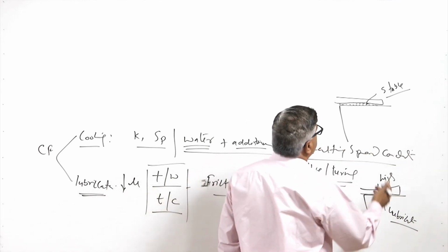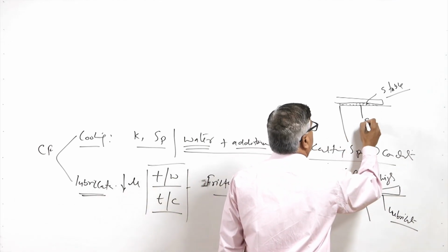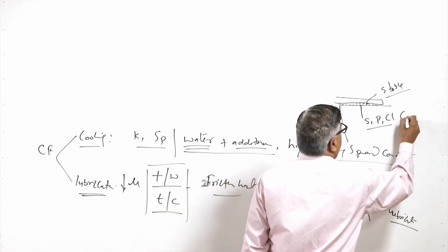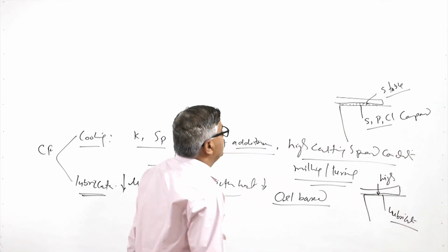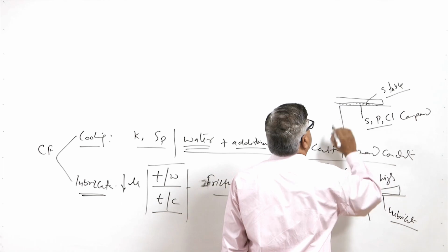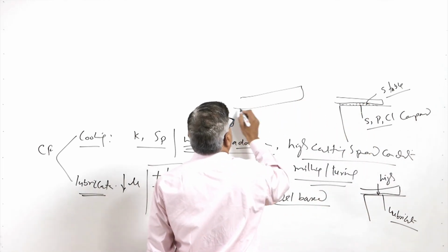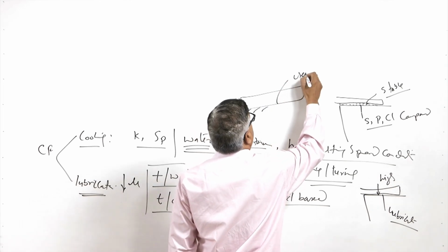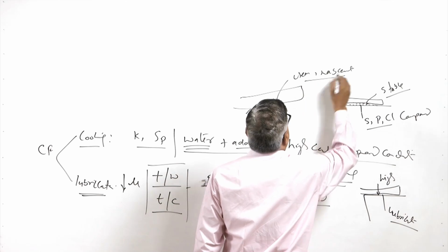And for this purpose only, the oil based lubricants are added with sulfur, phosphorus and chlorine based compounds. These compounds interact with the machined surface as well as the under surface of the chip, which is very clean, nascent and fresh.